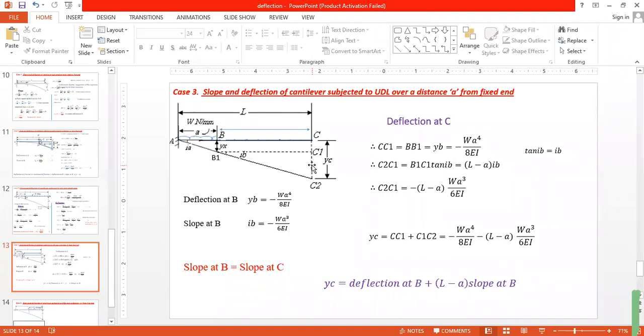See here, on a crankshaft there is a flywheel. The weight of the flywheel is very high, and that is one load on the crankshaft. If your crankshaft deflection is very high, then we have to consider that as a failure of the crankshaft.